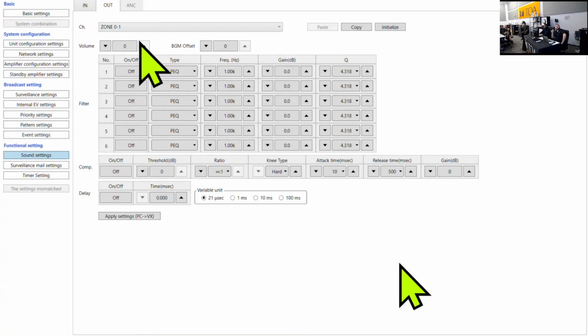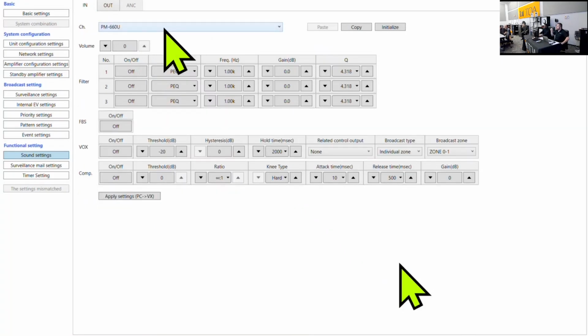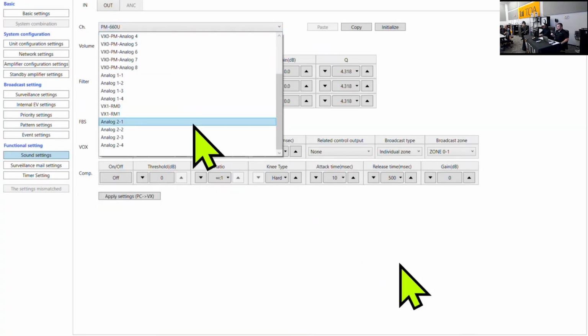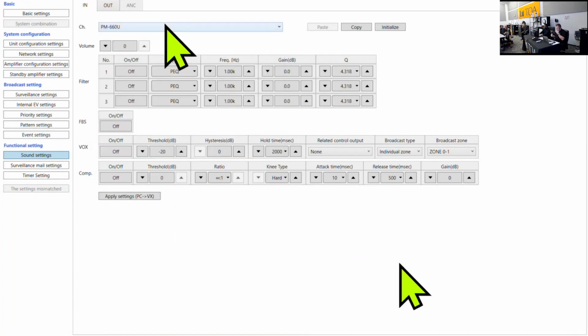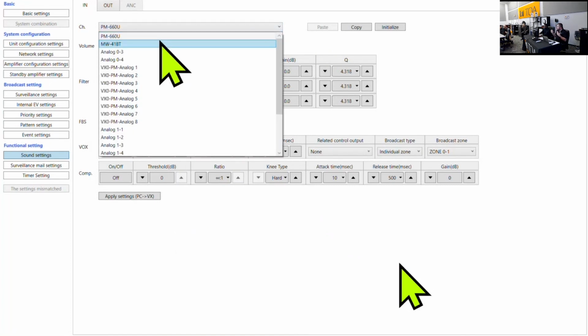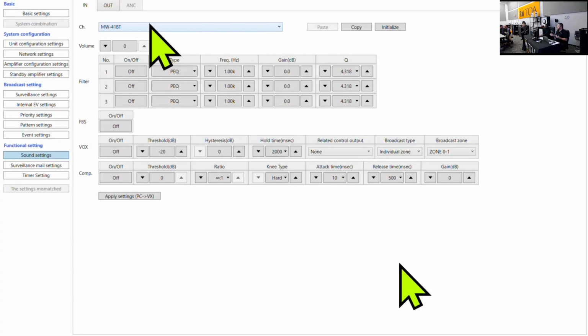And these DSP functions are for VX3004 only. This is a more powerful device that can do mixing and DSP functions that you can see here. VX3008 is for more zones, but just for PA and basic background music, and the 2016 is only for PA. So there are no DSP settings for the 2008 and 2016. It's only for the 2004. So if you want more flexibility, we usually suggest buying the 2004. More power, more flexibility, and DSP functions.